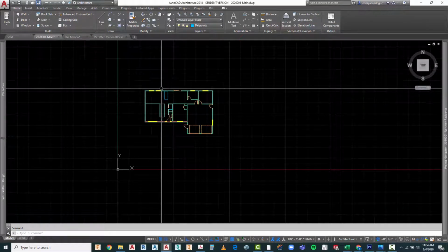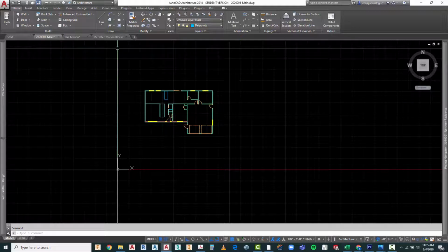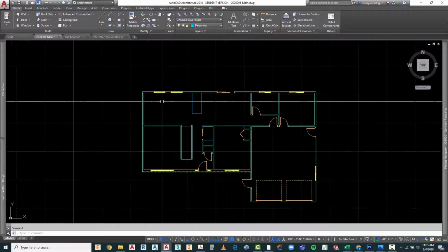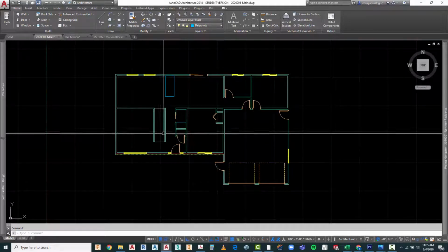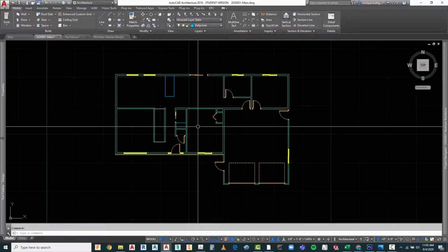The next thing I'm going to do is, based on the markups that we did and the red lines, there's a number of things that I need to bring in, whether they're toilet fixtures, sinks, there's going to be appliances for the kitchen, and we're going to be using all of those layers that we now have available to do a lot of two-dimensional line work. Since we are not going to be 3D rendering the inside of this house, we can bring in some simplified blocks that we're going to be using for our plans.